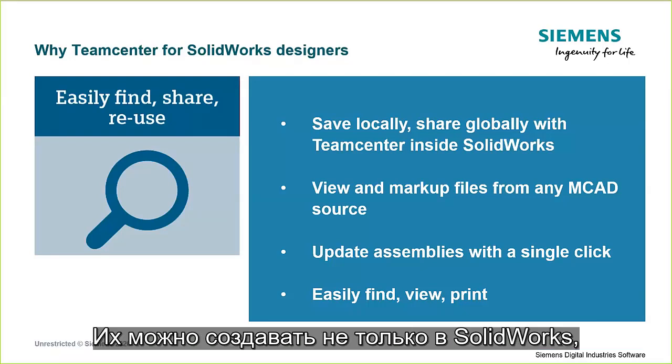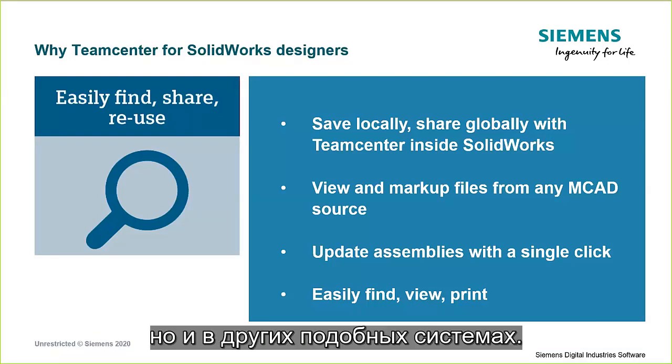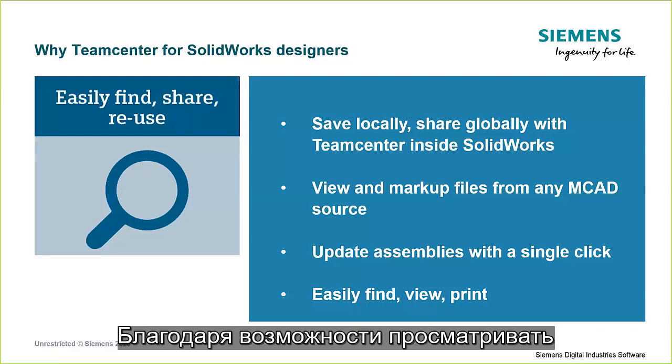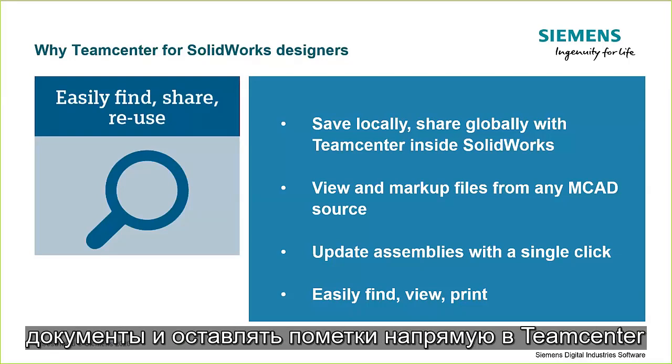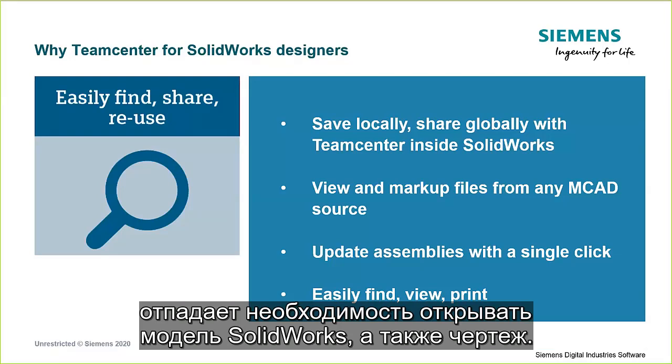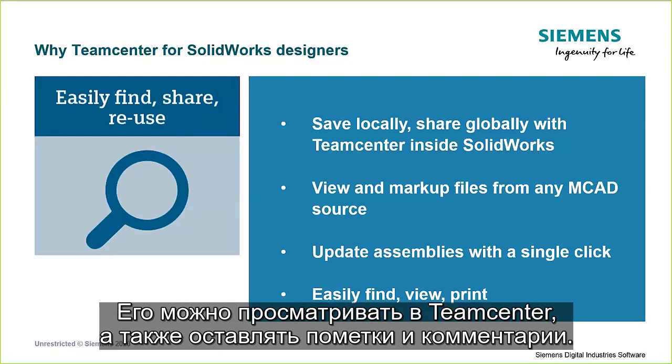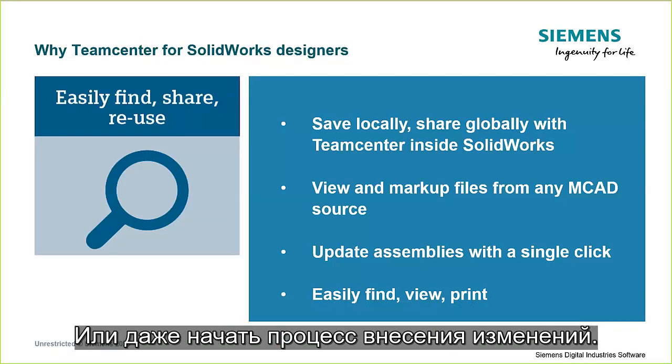Now, further with Team Center, you can view and mark up design documents. So those can be created from not only SolidWorks, but a variety of MCAD tools. So this workflow of viewing and creating markups directly in Team Center mitigates the need to fully open your SolidWorks model, or even your drawing. You can view the drawing in Team Center as well to put a markup on it or a comment, or maybe even to start a change process. You can do that all inside Team Center.